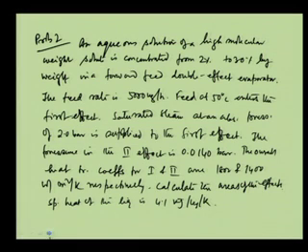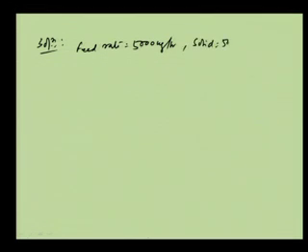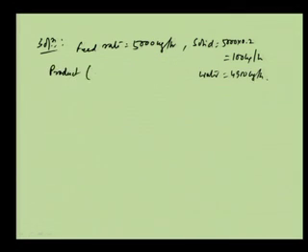So, now how to go for the solution: we know that feed rate equals 5000 kg per hour. In this, solid is 5000 into 0.02, and that is equal to 100 kg per hour. So, water in it is equal to 4900 kg per hour. Now, the product has got 30% solid.